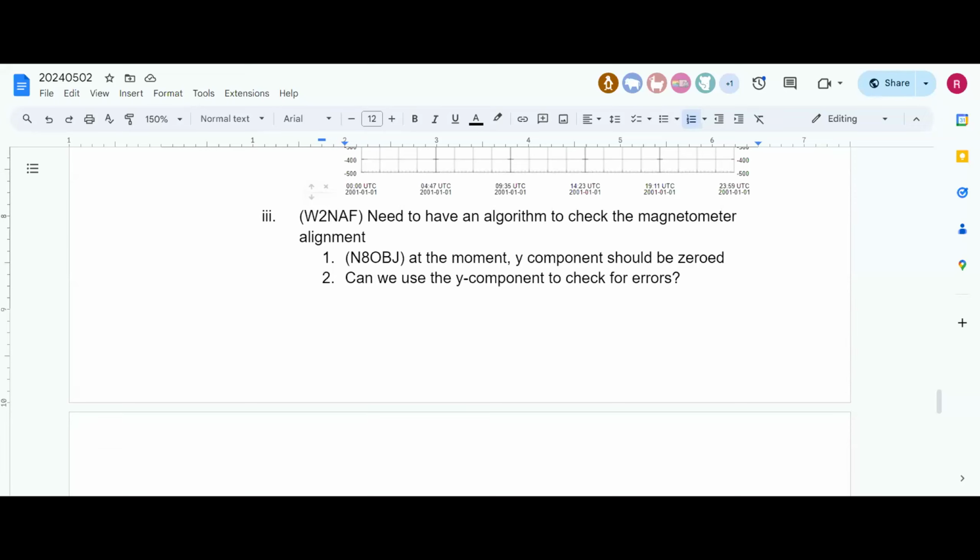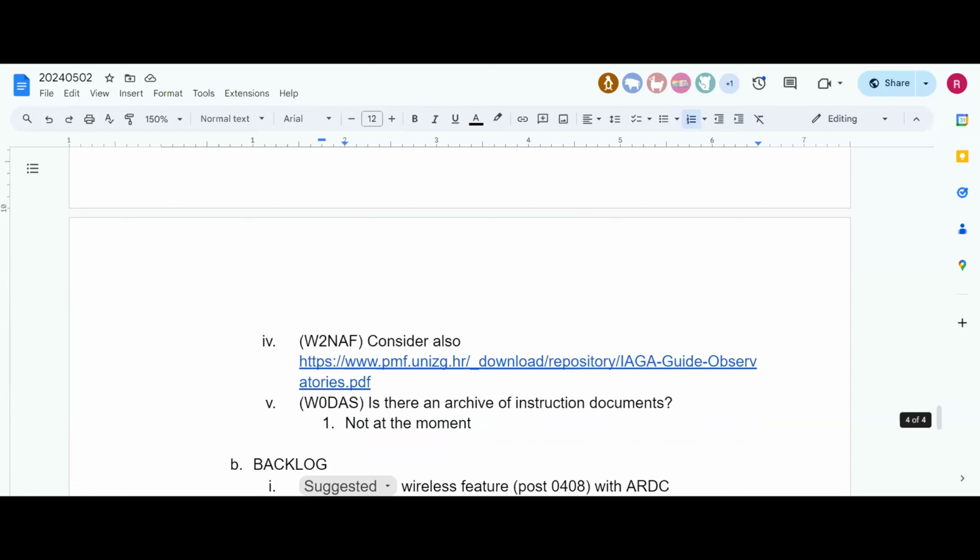Okay. The second part, being 2 feet under, doesn't make sense in this environment for 2 reasons. One, our frost level goes below that. It's generally considered to be 6 feet here. Second, we have bedrock, and it's going to be hard to get it even 2 feet down. Right. Yeah, mine is 3 feet down, and I could take it farther, but I didn't have a drill bit extender long enough to take it any farther.